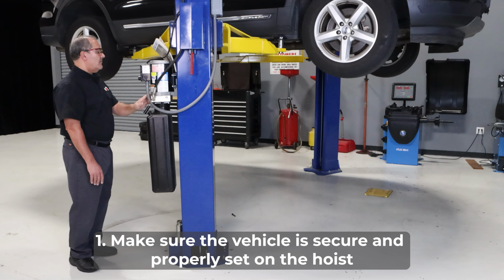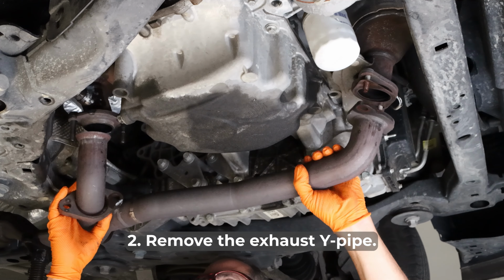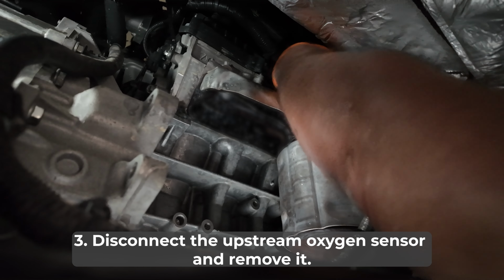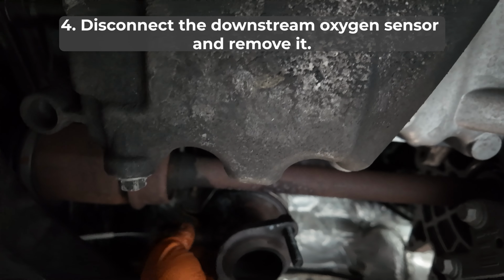First, make sure the vehicle is secure and properly set on the hoist. Now, remove the exhaust Y pipe. Next, disconnect the upstream oxygen sensor and remove it. Then, disconnect the downstream oxygen sensor and remove it.